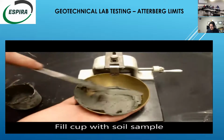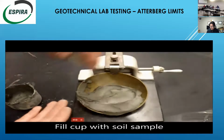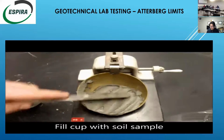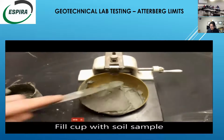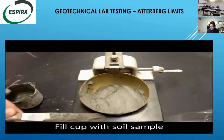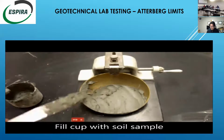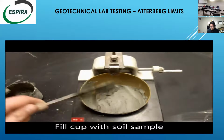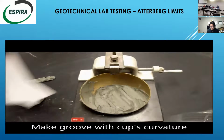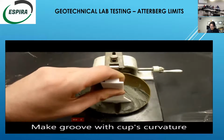First, a tare is massed and recorded. Next, a sample of the soil is wetted until it is about liquid. Next, about a 1/3 inch sample of the soil is placed into the brass cup. Using the grooving tool, the soil is scored down the middle, and be sure to follow the cup's curve, cutting deep into the brass. Next, using the crank, the cup is lifted and dropped at about 2 drops per second.